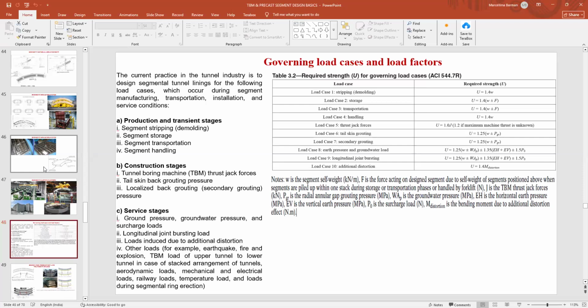This is not the same as our conventional NATM lining. In NATM lining, we are making a cast-in situ lining. Once the cast-in situ lining is over, the lining will take the loads. But in segments, there are lots of temporary loads before the segment is placed. So considering these temporary loads, the configuration of the ring or the number of pieces has been decided by the different country guidelines. We generally don't want to make a new arrangement.